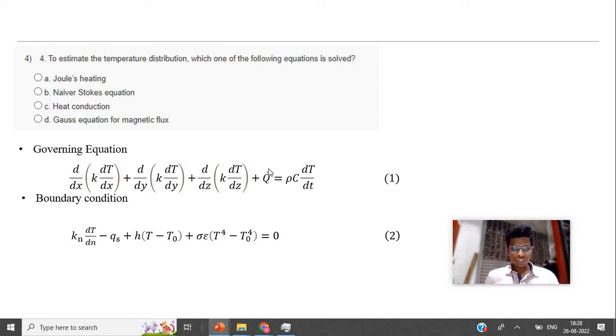So we need to solve this equation to get the temperature distribution. That is understood. This is a three-dimensional transient heat conduction equation. Since ours is electric arc welding or any deposition process, there will be an arc, and because of the heat generation, the metal will be melted and deposition happens, right? This equation I am basically explaining for arc welding processes like GMAW or GTAW.